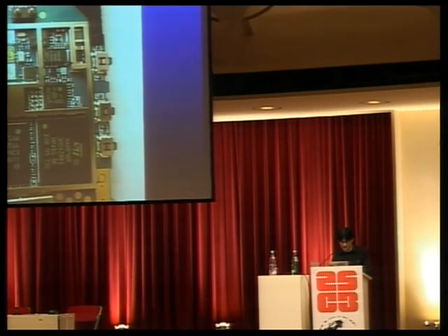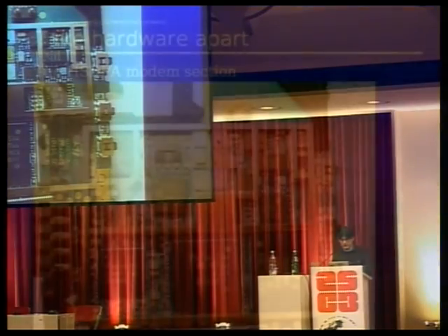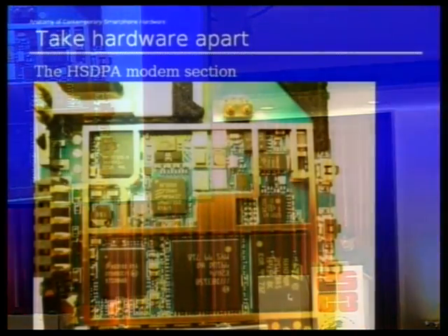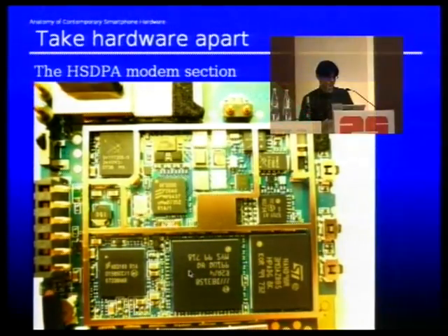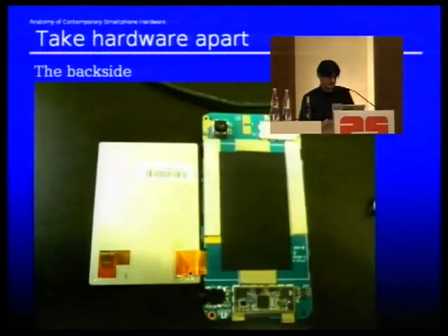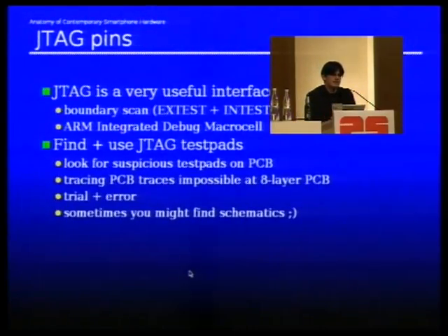For those devices like the RF3000 and the Sky whatever devices, you can actually find the data sheets if you Google for them. These are mostly the RFPA, antenna switch, all kinds of things like that. This section on the lower half is the digital baseband side. This is the flash and RAM chip and the baseband processor. Yeah, well, the backside is not as interesting. You can, as I said, Google for the various component identifiers, and then you might get an idea what those are and how they might be interconnected.